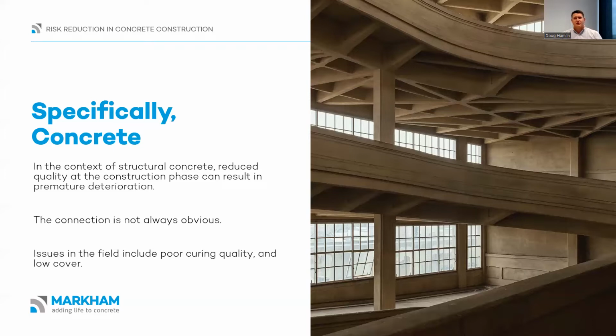When concrete cracks, over time it can let contaminants in through that concrete. Normally there's enough cover concrete covering the reinforcing steel to protect it against those. But where you've got poor concrete quality, that deterioration process speeds up essentially and can lead to premature deterioration.